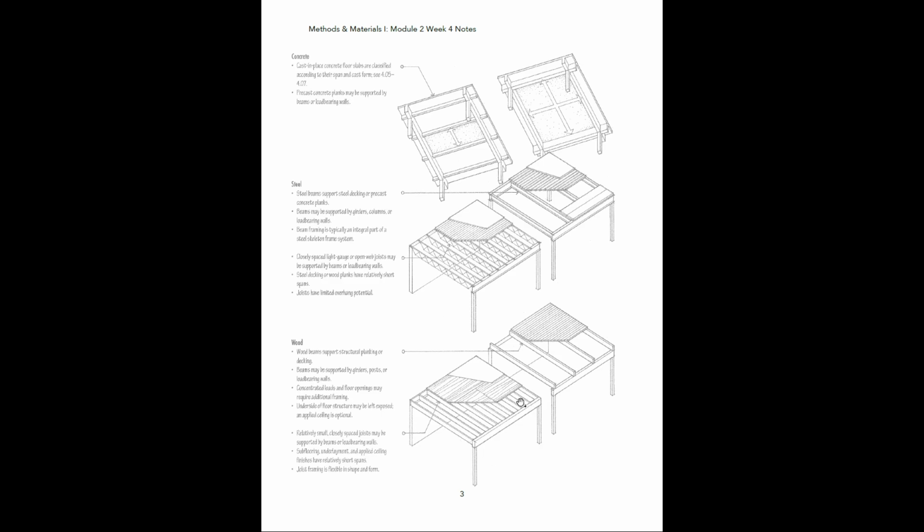But on top of this, instead of steel decking, obviously we're going to have our wood decking, okay, which is also known as subfloor. So we're going to have a subfloor that is attached directly to our wooden joists. And if you remember, like I said a couple slides ago, these joists are going to have a specific spacing value associated with them. So is it 24 inches on center? Is it 16 inches on center?